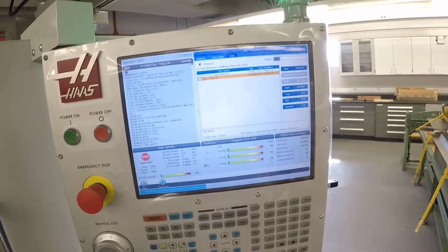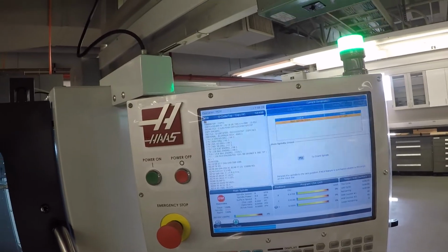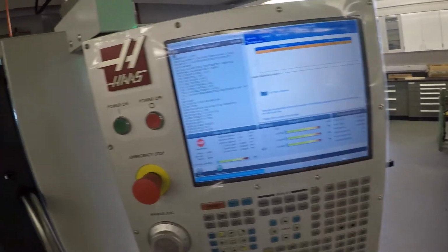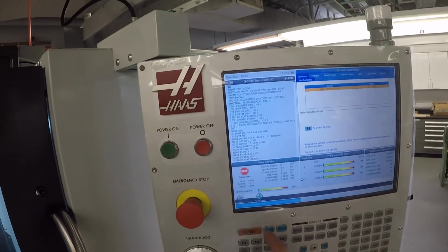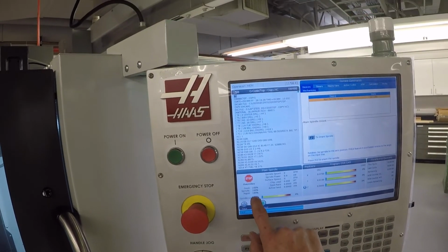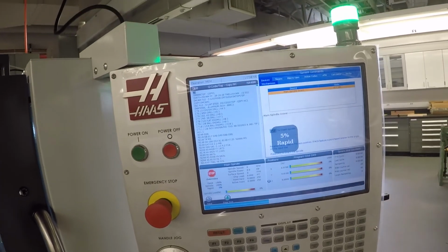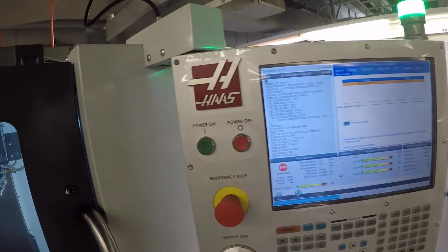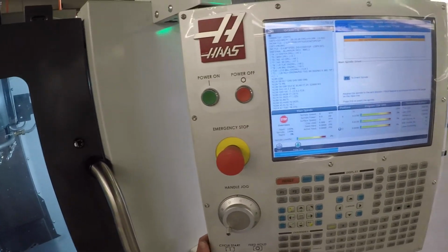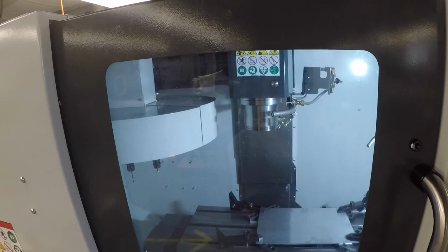So, oh yeah. If we go here, what I'm going to do is my spindle is on 400%, and so rapids. I'm not going to get into rapids and all that, but I'm going to run them at 5% right now because I haven't proofed this program. And while this starts, I'm going to keep my finger on feed hold just in case something happens. So here we go. Okay? See what happens.